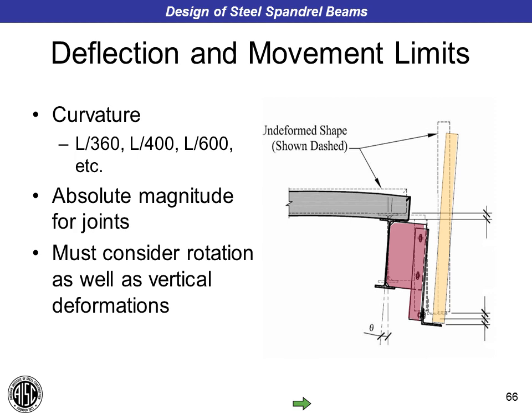So the appropriate deflection criteria for the spandrel beam really depends upon how much deflection the facade system can tolerate. The amount of vertical deflection the spandrel beam can undergo, for example, under brick veneer, might be limited to the span over 600 according to the Brick Institute of America, but that spandrel beam deflecting may cause the shelf angle to deflect, and the sealant joint that's below that shelf angle, as we discussed last week, may have a tighter deflection criteria than simply span divided by 600.